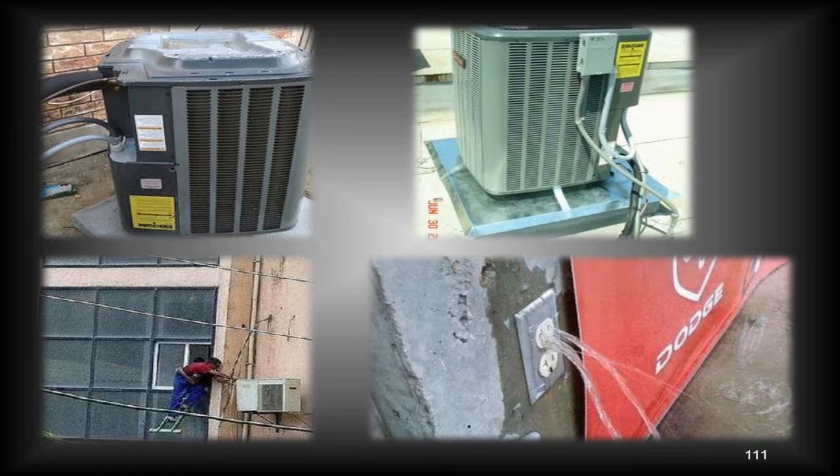Putting it on some kind of a fixed 4x4 coming up through the ground, or stabilized on the rooftop or something like that. You know, something other than on that condensing unit. I'm not going to say that this wasn't inspected and accepted, because some inspectors are fine with that, but other ones are not, and that's why you have to ask your inspector what they would accept and what they wouldn't.